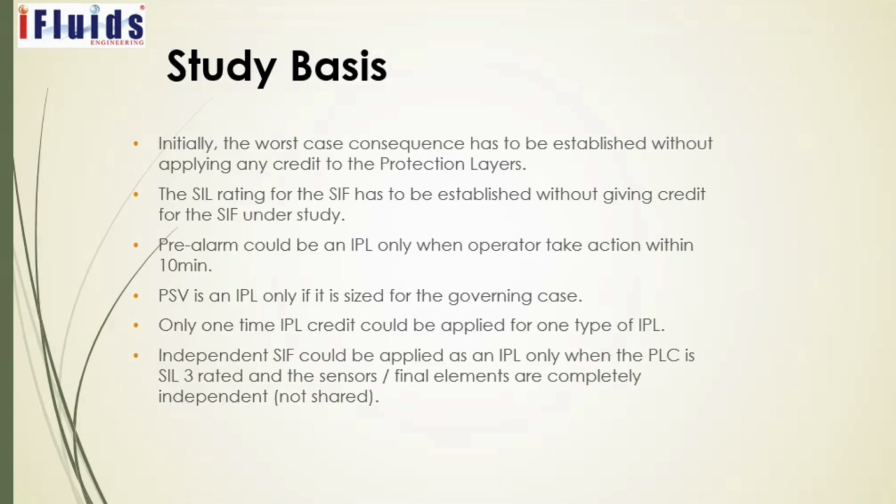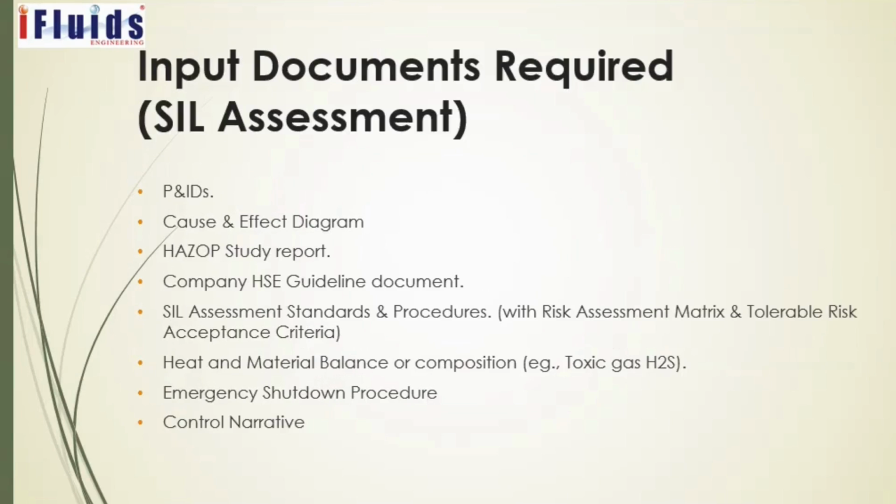Pre-alarm could be an IPL only when the operator takes action within 10 minutes. PSV is an IPL if it is sized for the governing case. Only one time IPL credit could be applied for one type of IPL. An independent SIF could be applied as an IPL only when the PLC is SIL 3 rated and the sensors and the final elements are completely independent and not shared.